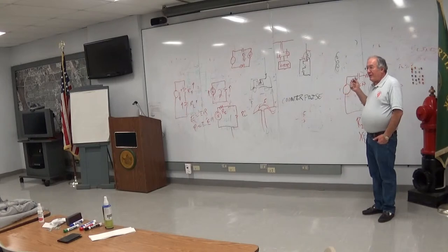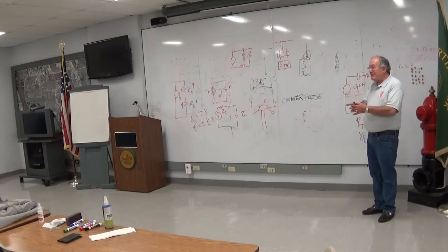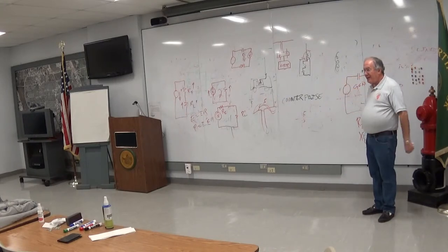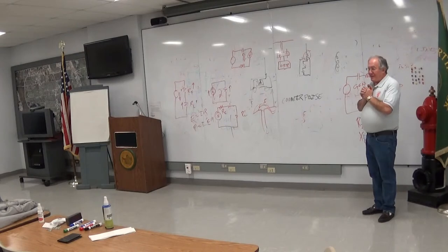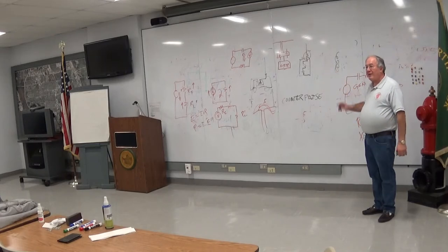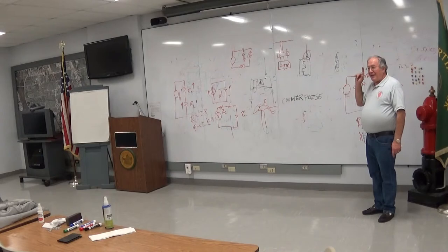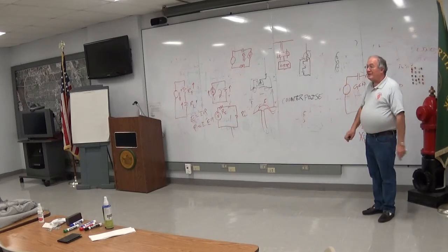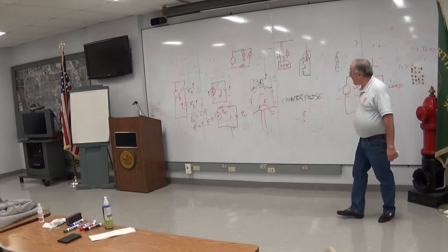And what you do to make up for the incorrect length is you have this matchbox and you add in the reactances that aren't there that have to be there to match what the transmitter's doing or compensate what the antenna's doing incorrectly. And all of a sudden your transmitter says, hey, I've got a perfect load. A perfect load is a resistor. No reactance. Remember, the reactances have to be equal and opposite. The resistances should be equal. The best deal is it looks like a resistor.